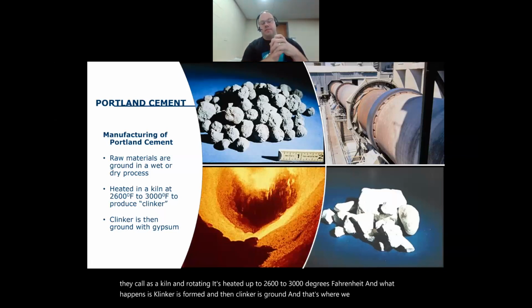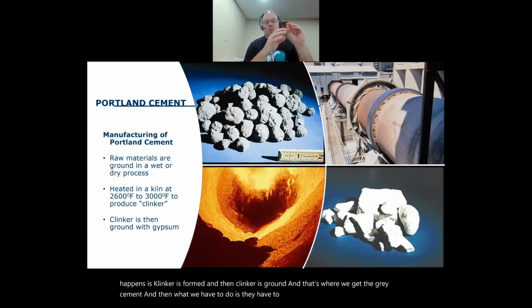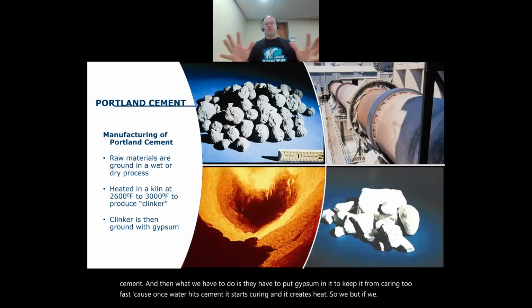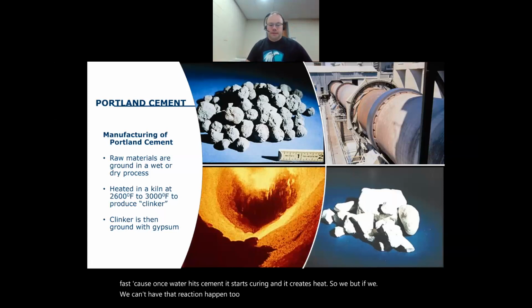Then they have to put gypsum in it to keep it from curing too fast, because once water hits cement, it starts curing and creates heat. We can't have that reaction happen too fast, otherwise we won't have time to work with the concrete.